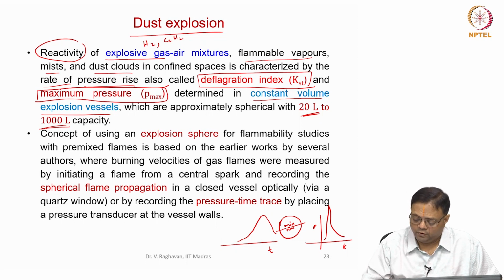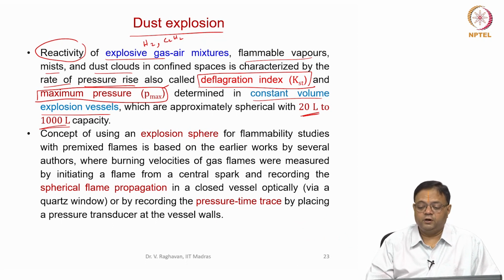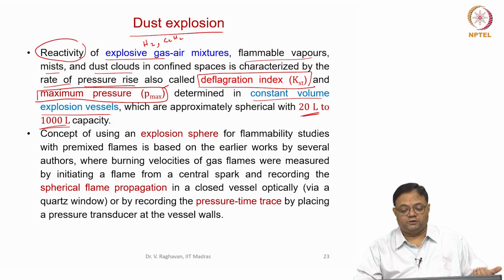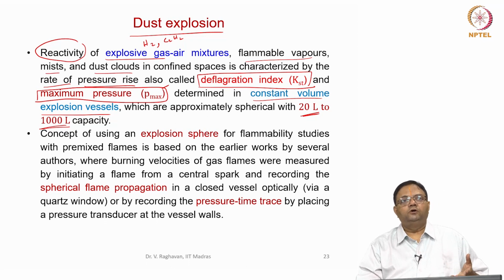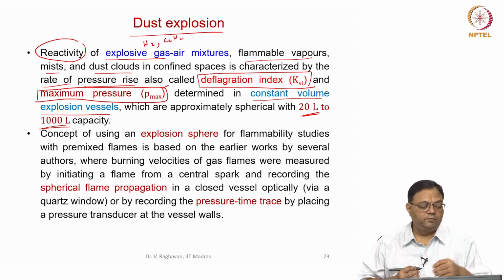Okay. So, there are standard tests to determine this, and these parameters, like deflagration index and maximum pressure, are important where you really consider applications having enclosed vessels in which combustible mixtures are handled.